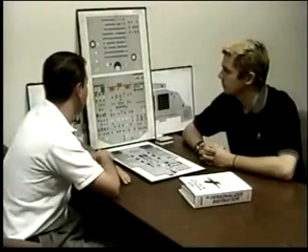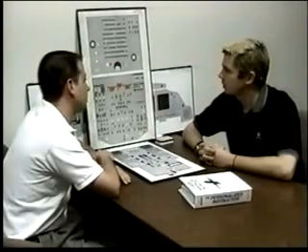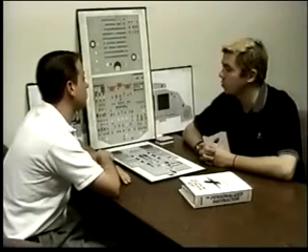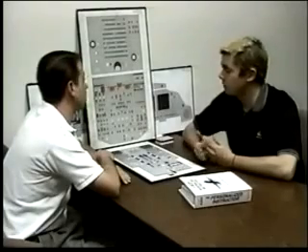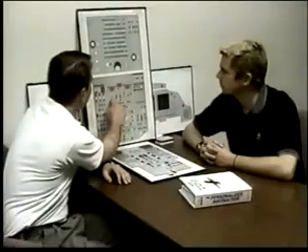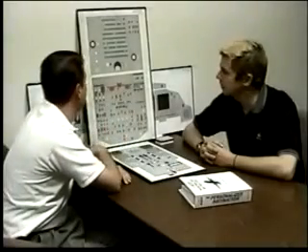Would you get a fault light with one of those 3 conditions in the PTU? Yes, I would. The PTU is only designed to help for low pressure in the system, so it wouldn't want to operate the system with a bad reservoir. Finally, the 4th condition for the fault light is low pump output pressure, in which case this is what the PTU is designed for.